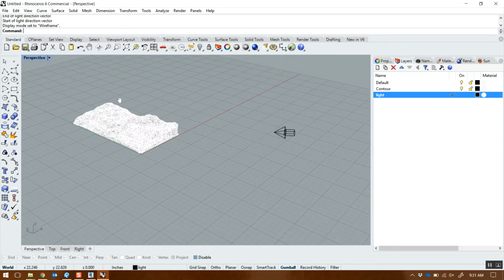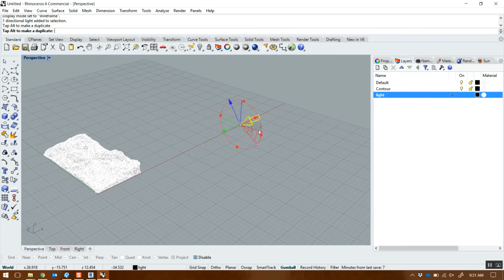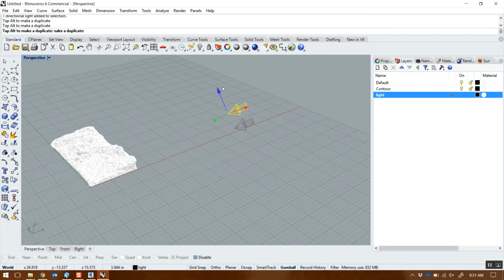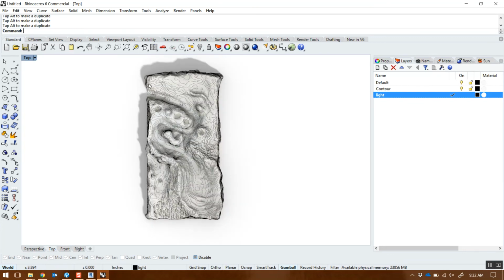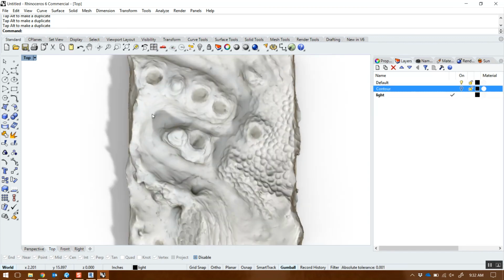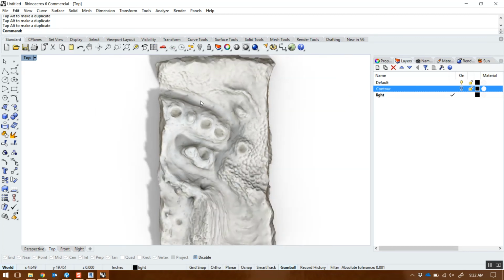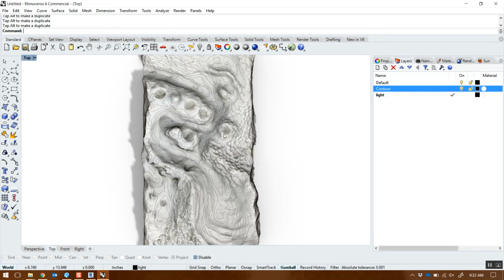Let's go to wireframe so I can see it. So move this up, rotate it downish. It's kind of pointing at it. So now it adds a little bit of light on this thing. You can see it adds the shadow to the little mounds here. So this is how you would do hill shade, right? Basically, you just add a light. It shades, lights the hill. Okay. And then you add your contours on it, and then it looks good.